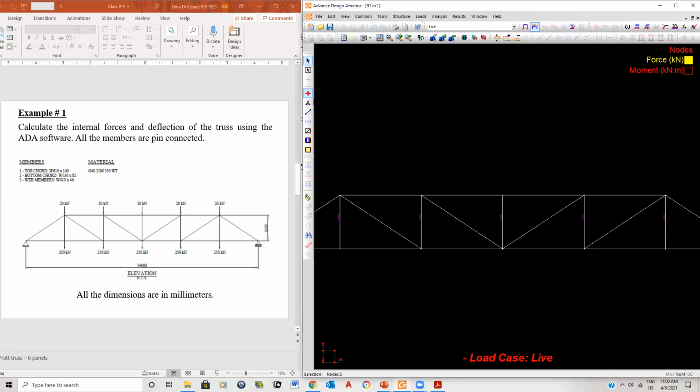I'm at nodes, and you activate the node here, right? Activate nodes, and then I selected all the top ones. Click. Now I'm going to do it again for the bottom ones. So here I'm at activate nodes. I'm going to pick all the bottom ones here. Now see, they're all purple. They've all been picked. I right click.